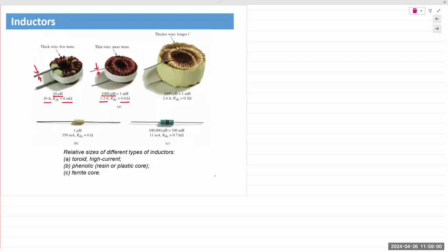Physical, we didn't cover it in this class, but I'm hoping that you came across it in physics, perhaps. Resistance R, physical construction of a resistor, is rho L over A. L is the length, A is the cross-sectional area. The thicker the wire, the lower the resistance. The thinner the wire, the higher the resistance. Okay. And the resistance matters for inductor.